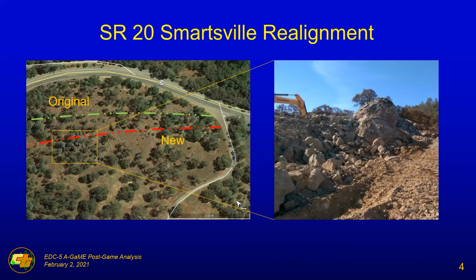This was an example of a project we were working on where we had some major cost overruns. We had done some seismic evaluations for excavation potential, and you can see where the original alignment was in green, and right up where this rectangle is, there is a boulder field. When we provided the original estimates of rippability for further down the slope, unbeknownst to us at the time, they changed the design alignment and put it right in the vicinity of that boulder field.